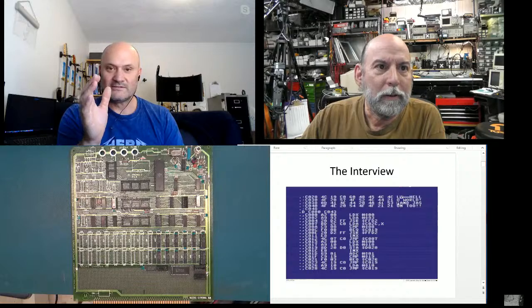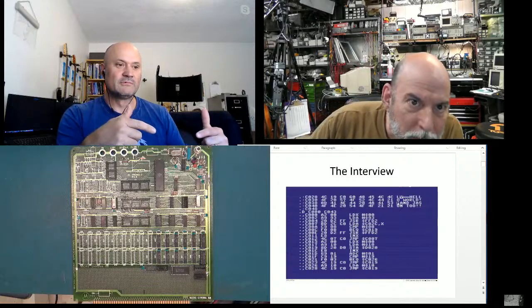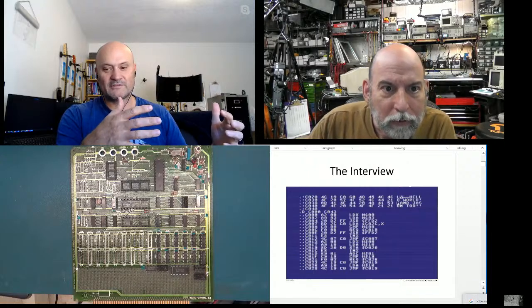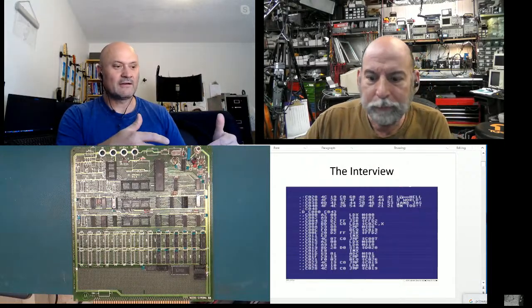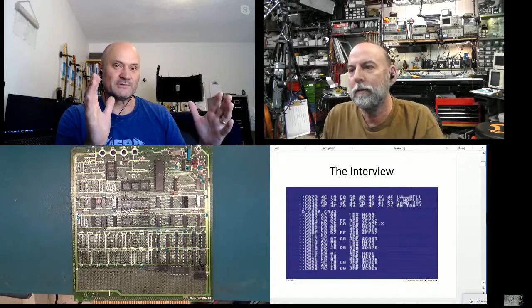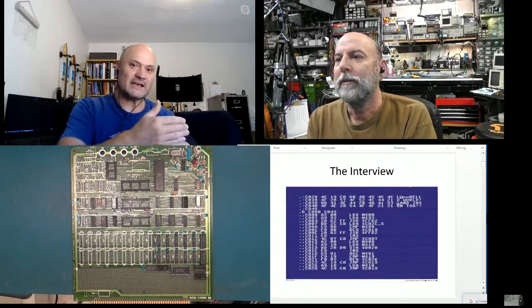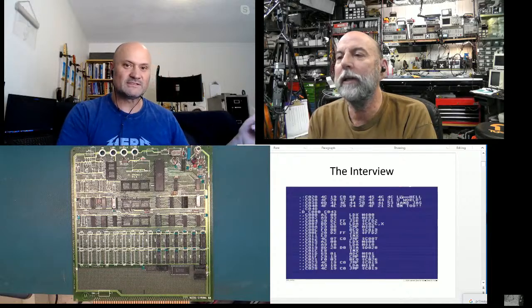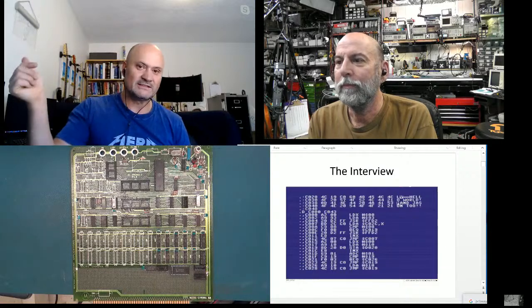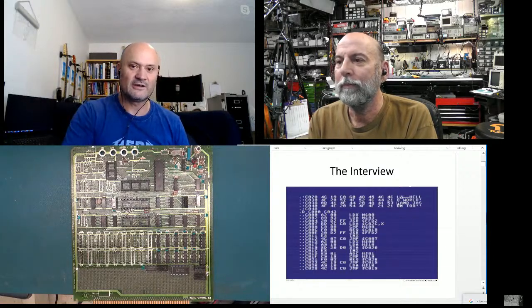The DAC would read out a line buffer. A buffer is another word for memory, from your video memory, and the thing that made video memory special was it was dual port, so the DAC could read from it, but the host bus or CPU could write to it in parallel, and the DAC would read from it and spit out the serial analog for the video.